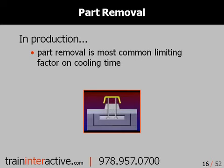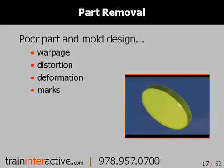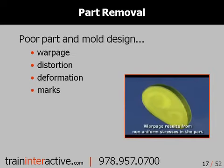In reality, using a stripper ring or stripper plate would be the best way to eject this part, as it would allow us to locate adequate water lines very evenly so that now we can distribute ejection forces evenly across the perimeter of the part. When ejecting any part, it's important that we do not distort the part as it's being ejected or introduce stresses that will cause the part to deform in its application. This is why stripper ring or sleeve ejection is used to eject this type of part geometry.